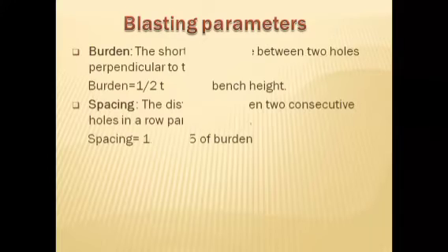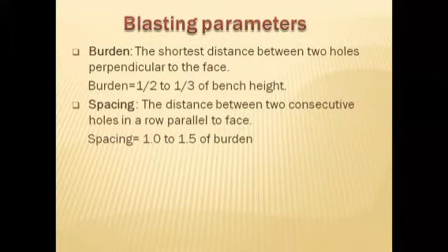Blasting parameters. Burden: the shortest distance between two holes perpendicular to the face. Burden ratio is 1/2 to 1/3 of bench height. Spacing: the distance between two consecutive holes in a row parallel to the face. Spacing ratio is 1.0 to 1.5 of burden.